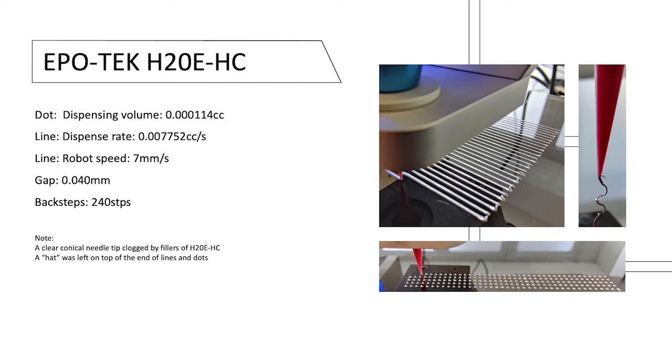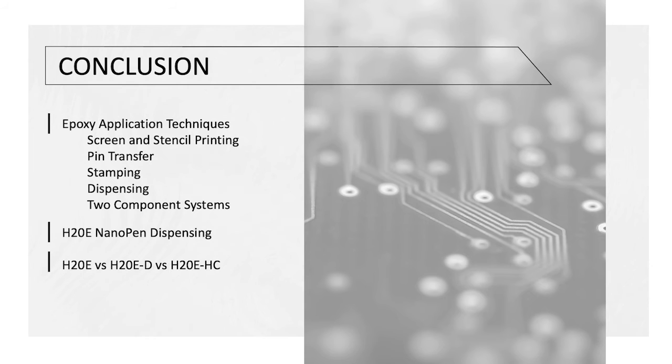You can see in the lines tailing, and again, evidence in the top right corner that the silver-filled adhesive was forming a string-like material coming out of it. This kind of tailing can be a serious issue with small dot dispensing and potentially causing shorts within a system.